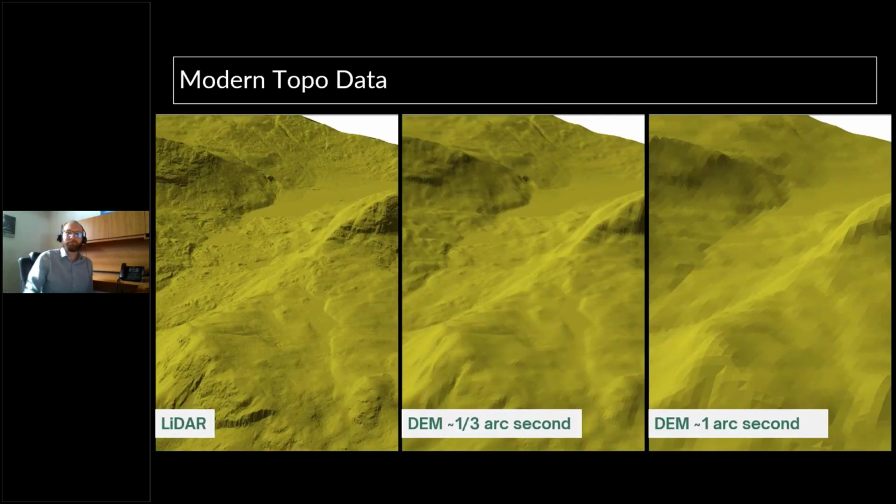Now, that preliminary workflow can be and has been improved upon, and become much more efficient. One of the big contributors to that is the availability and the advances of remote sensed topographic data. When we talk about remote sensed topographic data from a road design standpoint, the big buzzword that comes to mind is LiDAR. LiDAR is the preference of many planners and designers, and that's for good reason. It's suitable for bulk acquisitions. It's often publicly available. It can be very accurate, so accurate to a point where you can rely on it for your construction level designs.